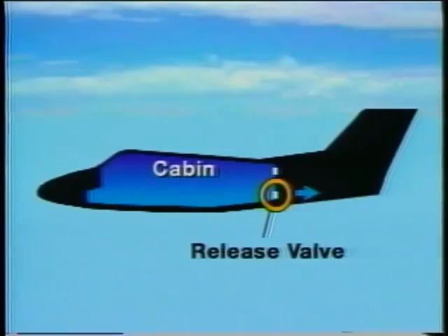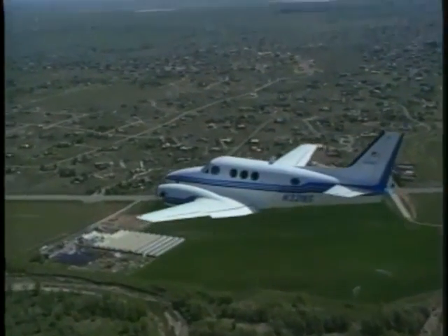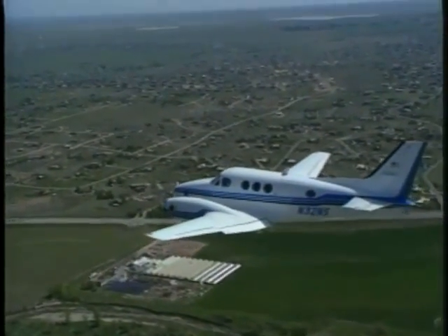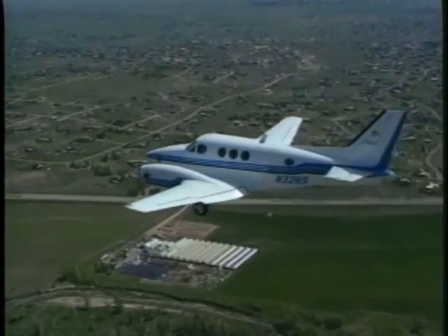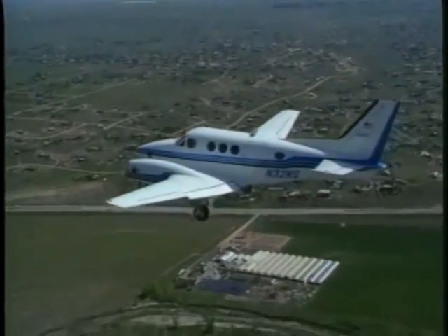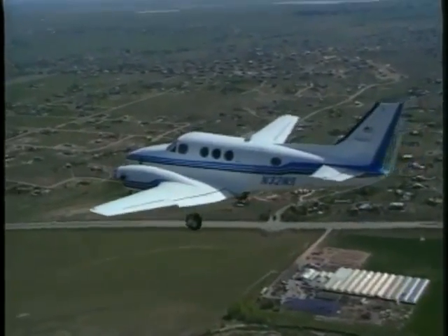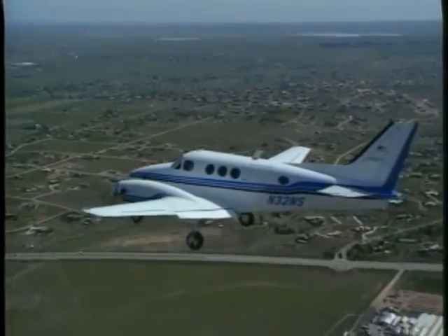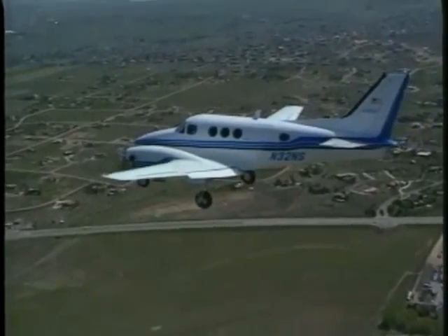This valve can also be connected to the landing gear safety switch so that any time the gear is down and the switch is open, the cabin depressurizes. It may also be manually opened in case a turbocharger fails and contaminated air enters the cabin.